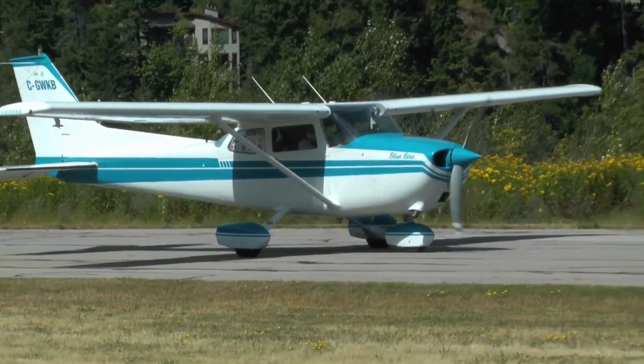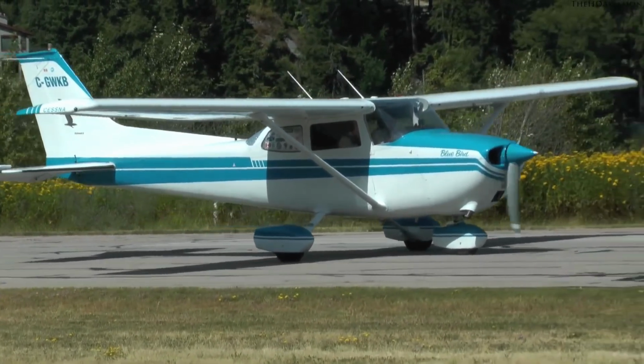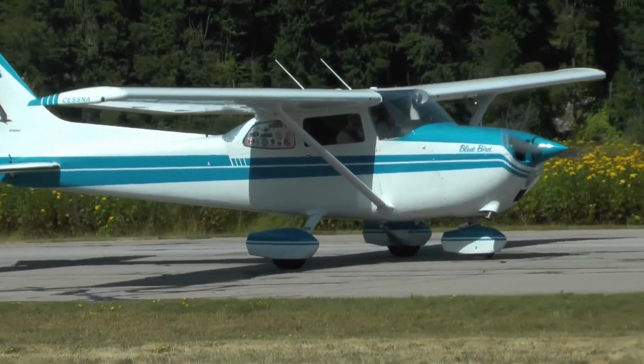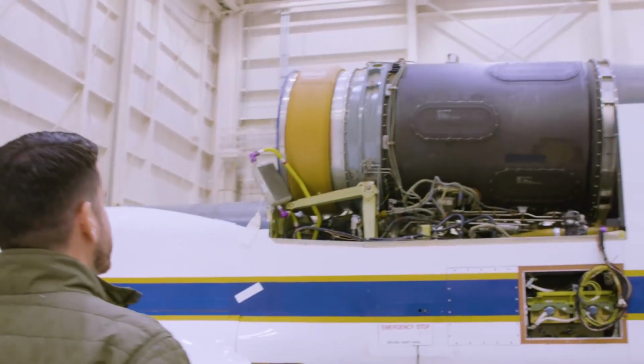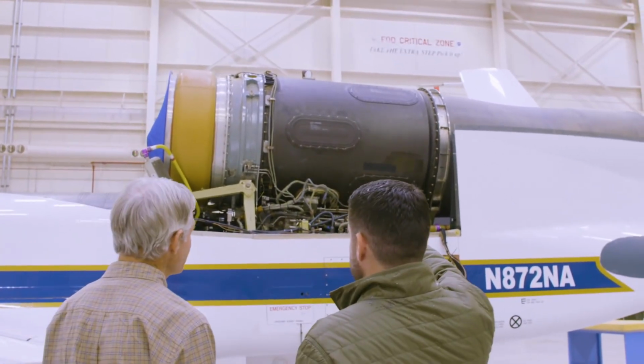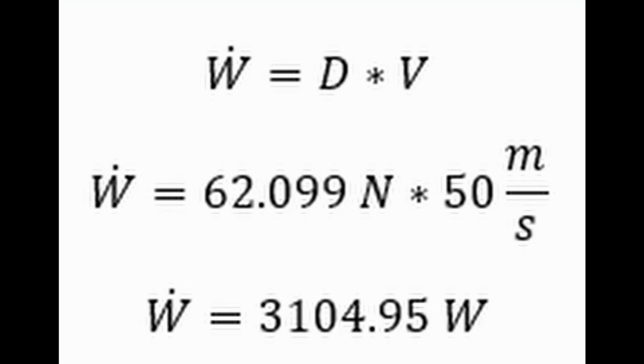Next, we want to calculate the power requirement and propulsion estimate for the aircraft. The power of an aircraft is defined as the product between velocity and drag force. For this calculation, a summation of the drag force acting on the wings and the fuselage was required. The power at cruising conditions was determined to be 3,104.95 watts. The selected propulsion method for our UAV was by propeller.